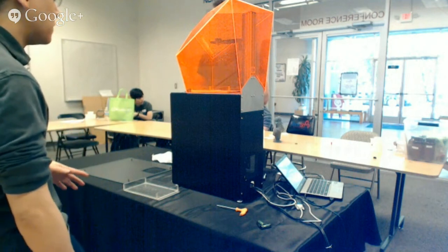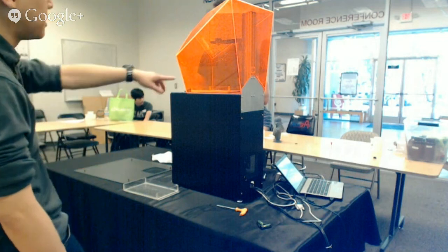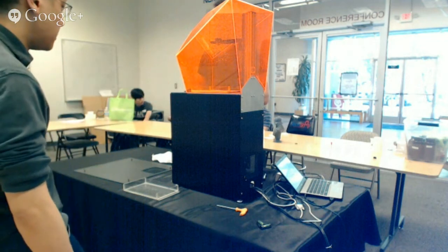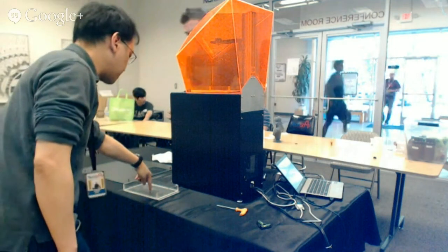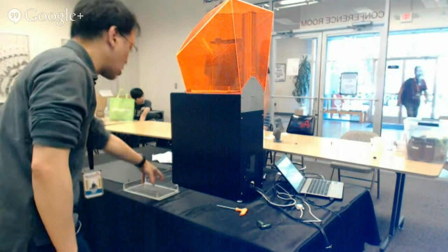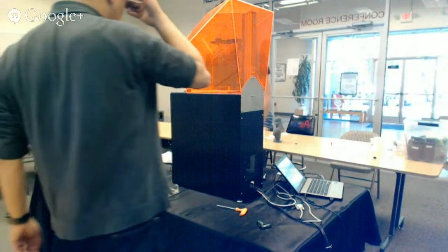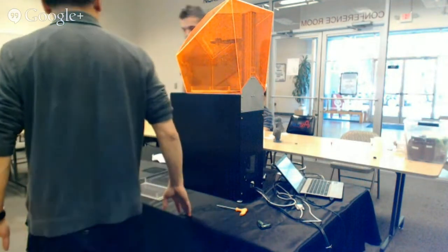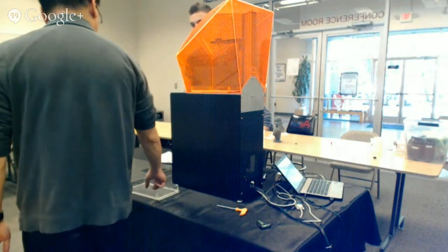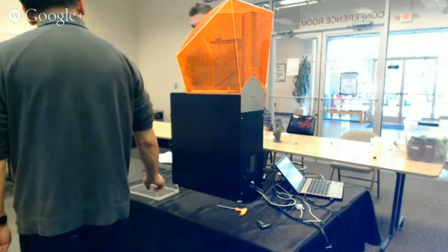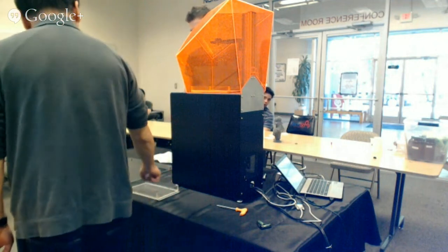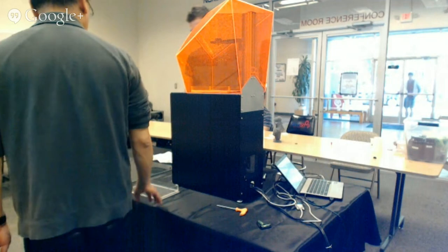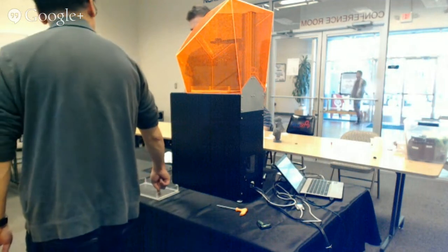With bare silicone, if you really overexpose it, then the silicone will become chemically fused to the part, and then you just keep going until the silicone tears off, tears a chunk of it off. And that level of stickiness will never happen with the Teflon. Teflon's minimum stickiness is higher than the minimum stickiness of silicone, but there's a max limit. So you're never going to get any kind of chemical reaction.